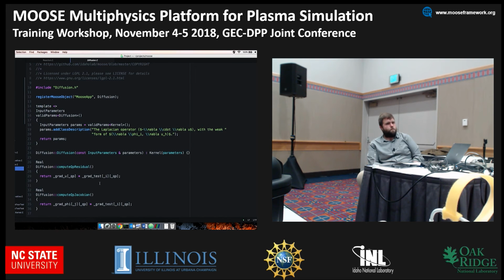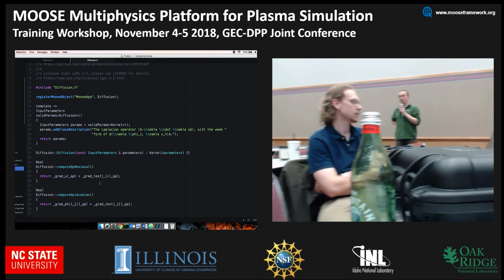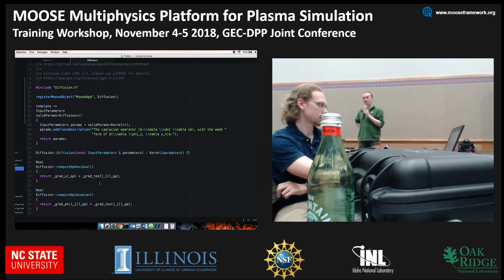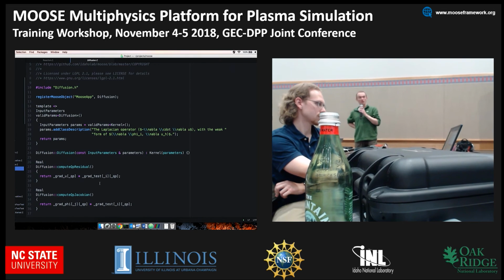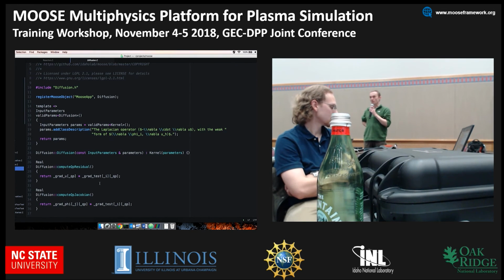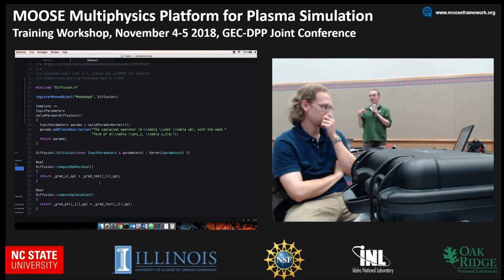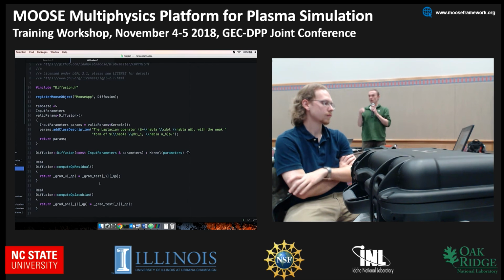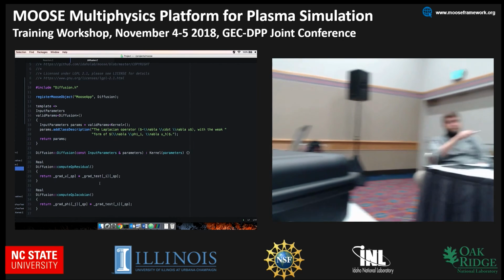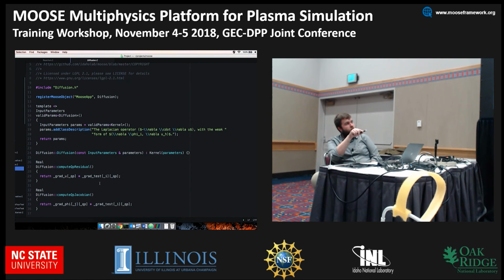Is that philosophy, like in Galerkin? Like you interpolate between solutions, right? Sure, in the nodes. And you said both the interpolation and the test function is the same, is one on the phi and test is that when you actually run a system of equations and each of your variables has a different finite element type, your phi is going to be different when you're doing the Jacobian, the off-diagonal Jacobian block. Okay? So something needs to happen inside MOOSE. And it's easy in this case because we are taking the derivative with respect to u sub j and getting this.